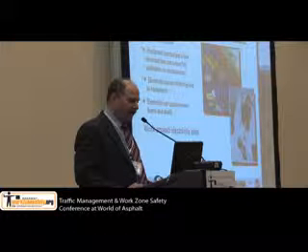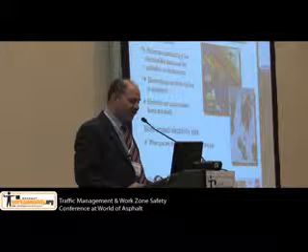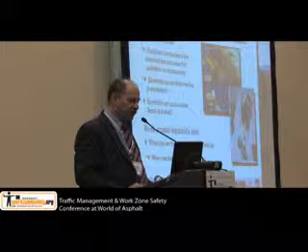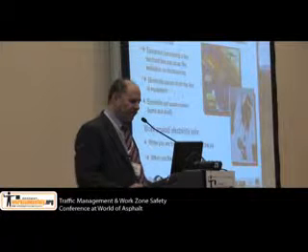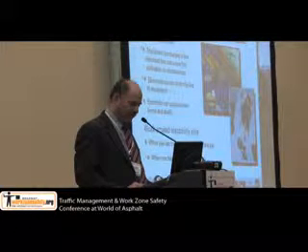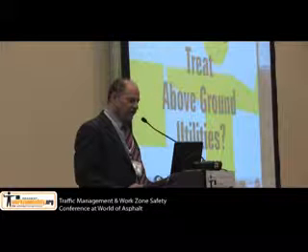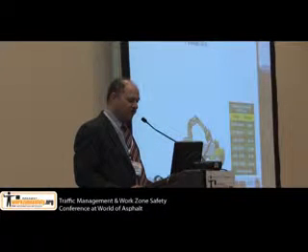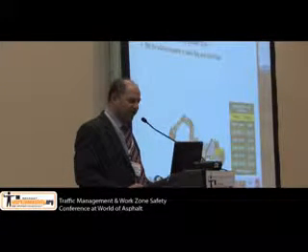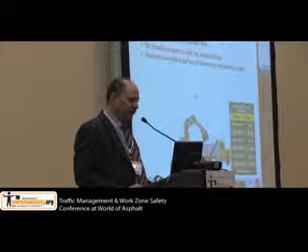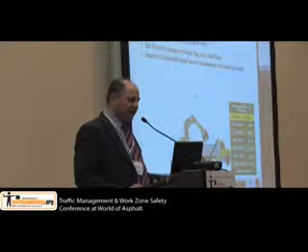And it can cause severe burns and death, and you should only work around electricity if you're trained in all aspects of the job and when you have reason to be there. Talk about above ground utilities, which are probably the major problem. We have the chart again. Get the utility company to mark, flag, and shield the lines.